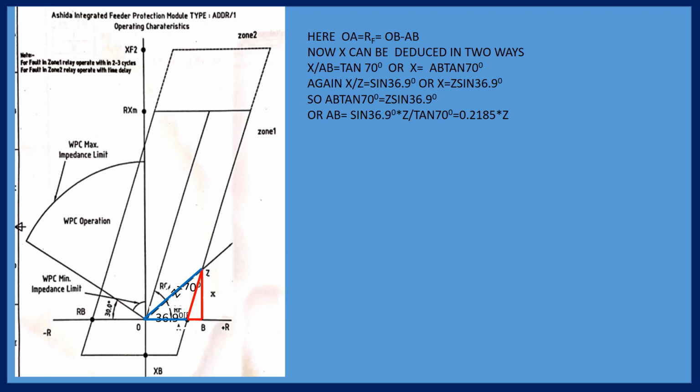If your earthing is not proper, then this will affect the surface of the TSS ground, the TSS yard. Then in between your two steps, the voltage will be severe and you will get shock. Simply in between your two foot steps, you will get shock.